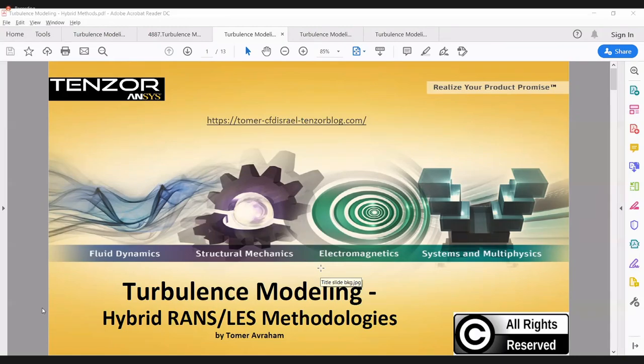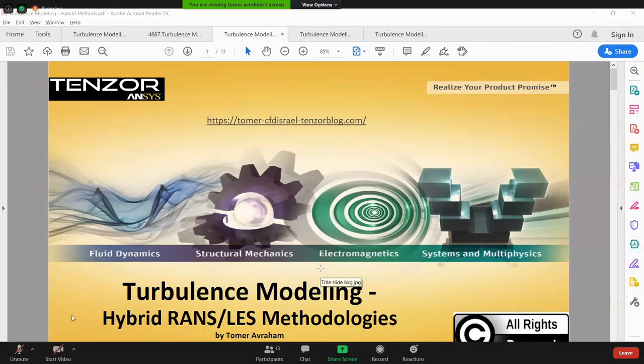By monolithic I mean you use one equation. That's the detached eddy simulation, like the Spalart-Allmaras. The funny thing in large eddy simulation, and I guess most of you know it, is that it's not closed. I mean, in two equation models, it's closed, right?